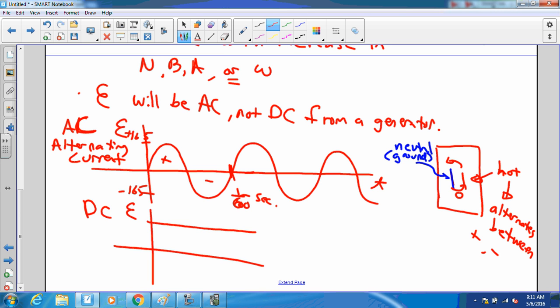The second reason, by the way, we will get to next week. The second reason that AC wins out over DC is that it turns out that a transformer, which is the component that we'll look at next week, is easily able to take AC at one voltage level and turn it to AC at another voltage level, so that you can transmit.